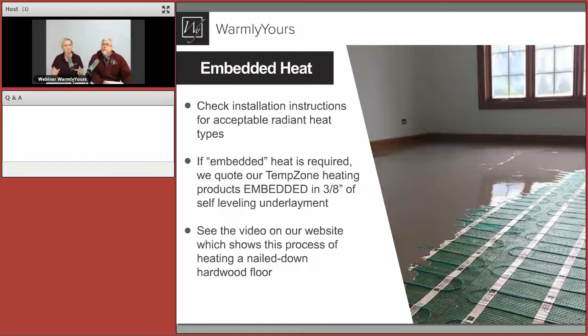So there's two ways you can install the Temp Zone product. One is embedded with self-leveling. And one question that we have from Debbie is, what if it's embedded only 1/8 inch with self-leveler? And I think the correct response is, as long as it covers the heating element completely, we're fine with that.